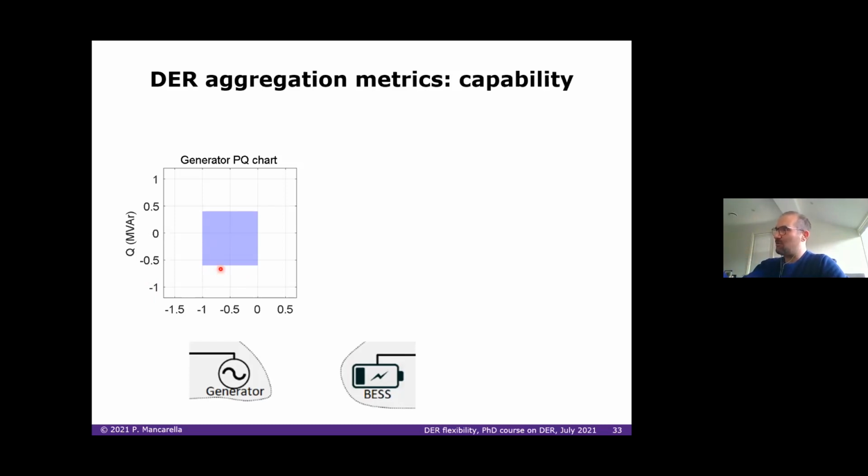If you export power as a generator, then it would be negative. And then we're neglecting here the minimum stable generation level. Otherwise, you would only have 0 or a certain level, and the operating region would be completely non-convex. It would be a disconnected, disjointed region.